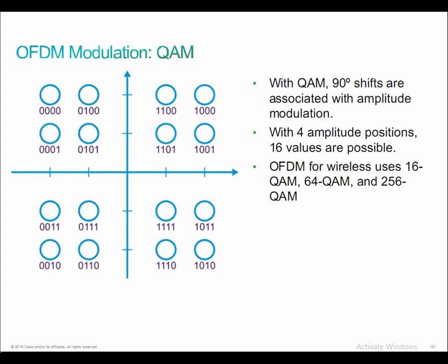Okay. Remember, we have the 4 bands for control, and then we have the 12 bands for the sideband channels and the center band and so on. In any event, 500 kilobits per second per carrier. If I multiply that times the number of carriers, you're going to get your 24 megabits per second. And there's only 48 carriers. Even though there's 64 of these subchannels within the 20 megahertz wide band, we only have 48 carriers of actual data.